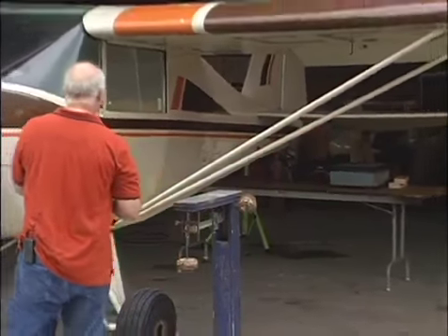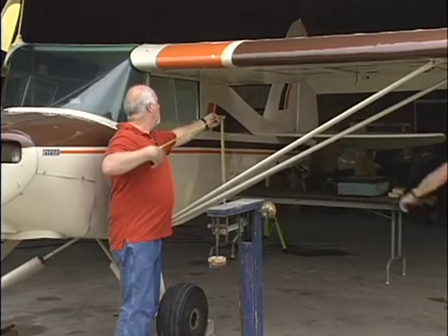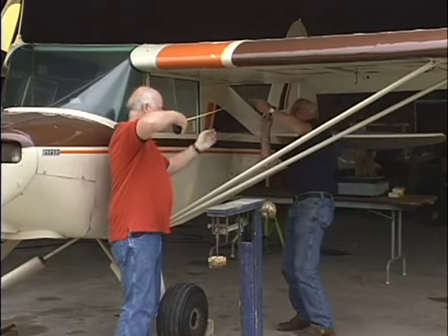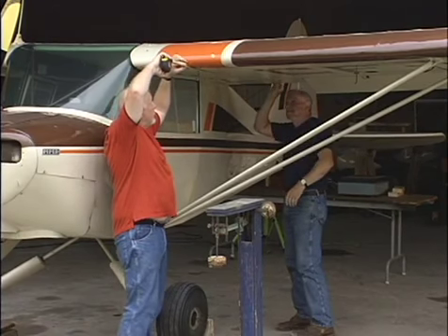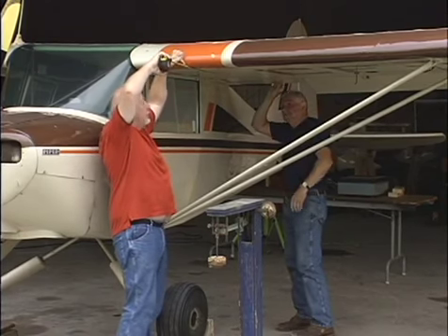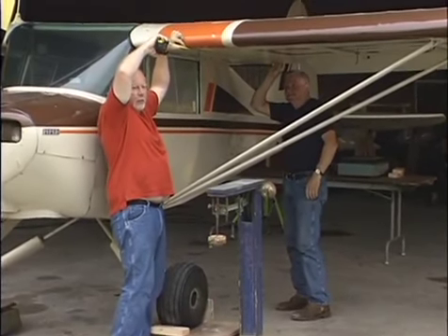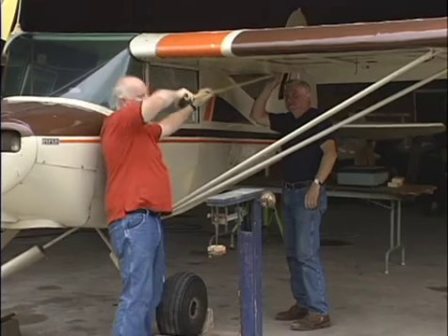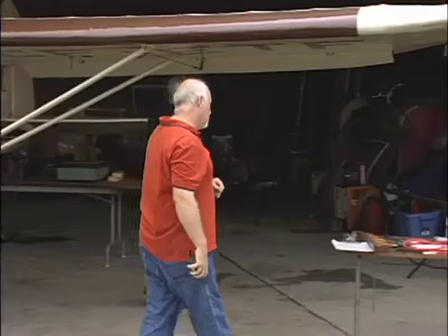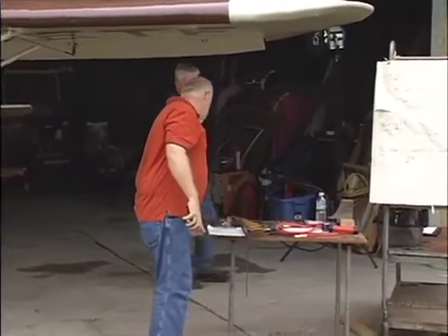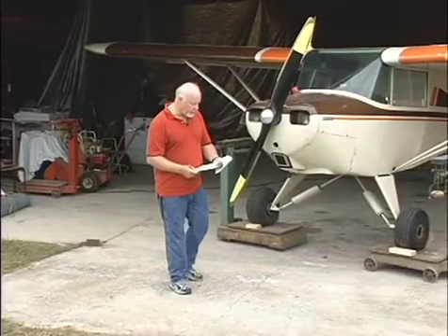The wing chord length, when it was measured out, I took the plumb bob and I dropped it down, and I took a measurement of what the chord of this wing is. And the chord of the wing worked out to be 62 3/4 inches long.